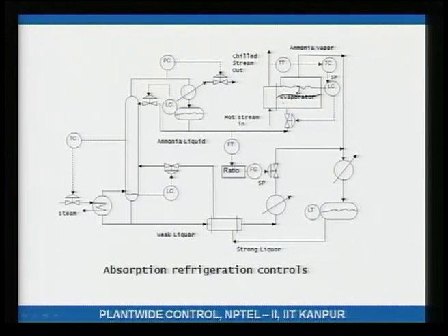Oh, what did I do here? I think I described the level controller wrong. See, this is the feed to the evaporator. So, if you want to reduce the level, what you would do is pinch this valve, giving less flow.